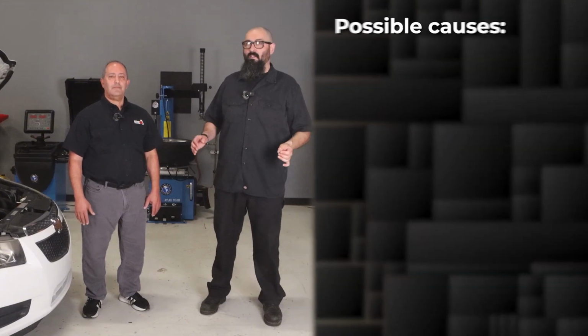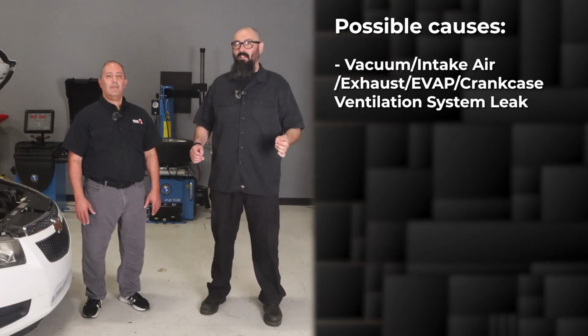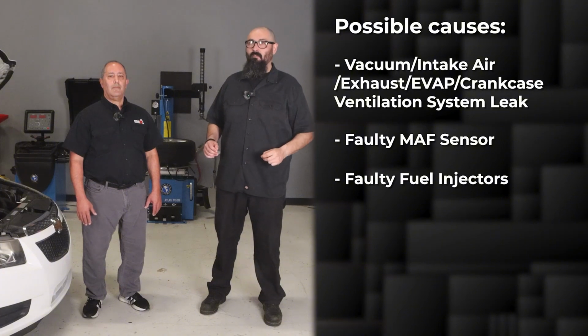Now, for P0171, there are several possible causes, including vacuum, intake air, exhaust, EVAP, or crankcase ventilation system leaks, a faulty MAP sensor, that sort of thing. If any other trouble codes are stored, make sure you diagnose and repair those first. Do not continue troubleshooting this code until all related faults have been corrected and taken care of.